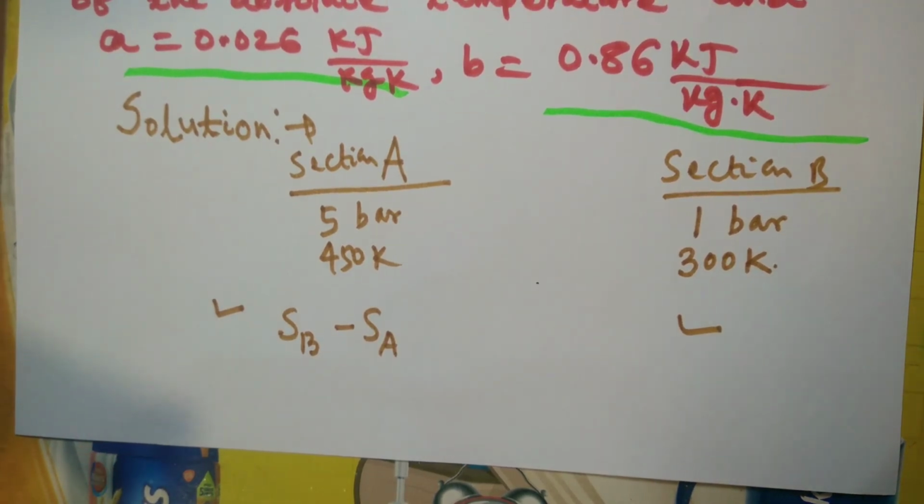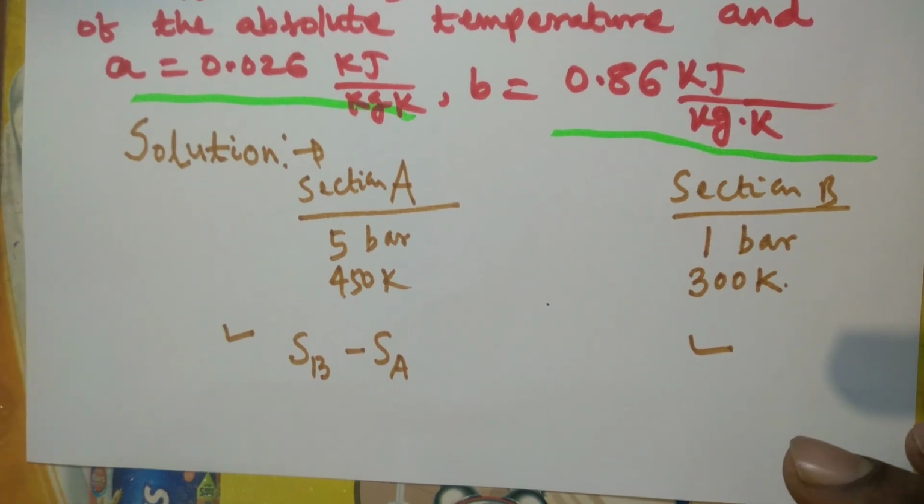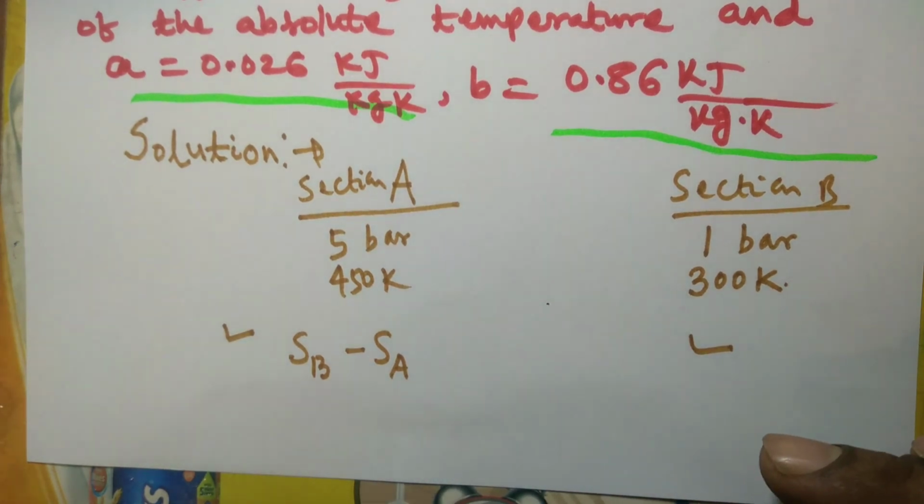In fact, we want to calculate the change in entropy of the universe, and in this case this machine is an adiabatic machine, so no heat flows towards the surroundings, nor any heat flows from the surroundings to this pipe, so that the change in entropy of surroundings is here 0, because no heat interaction takes place between system and surroundings, because the machine is adiabatic.